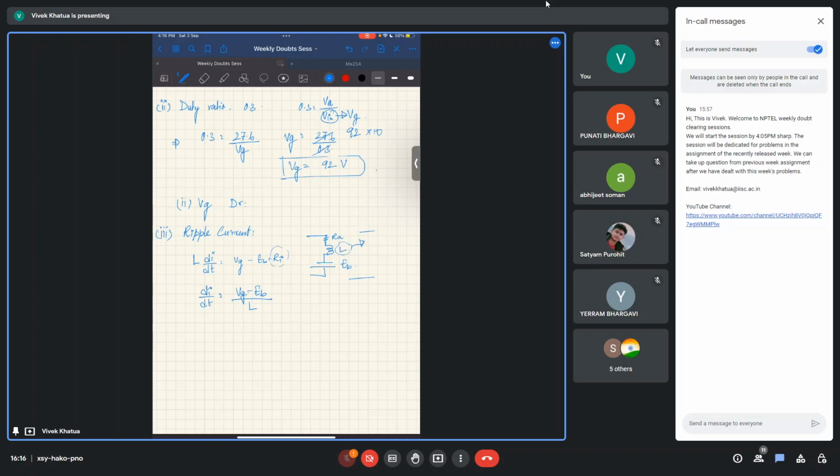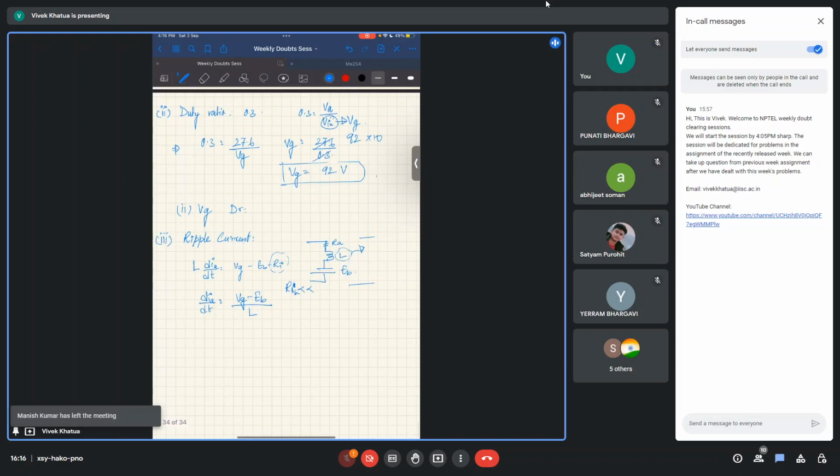Here, since we are taking R times IA, the armature current, to be really small, it's really less than Vg minus EB. For a given omega, we know that back EMF will be constant. So this is nothing but your slope, right?